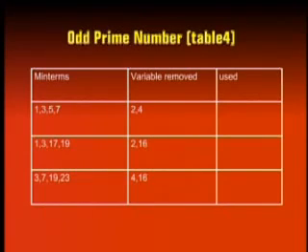There are 3 prime implicants in table 4 and 5 prime implicants in table 3. The 8 prime implicants are represented by the product terms A bar, C bar, D, E; A bar, C, D bar, E; B, C, D bar, E; A, C, D, E; A, B, C, E; A bar, B bar, E; B bar, C bar, E; and B bar, D, E.